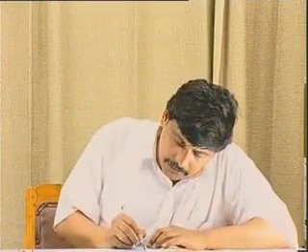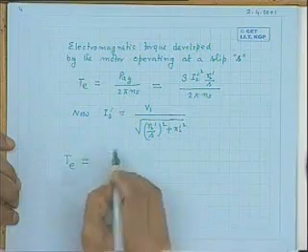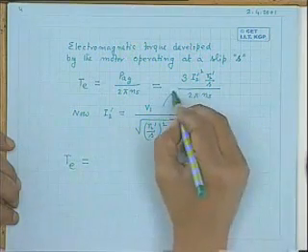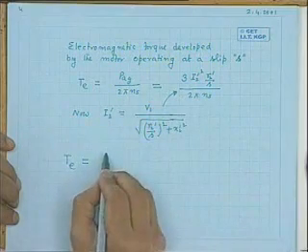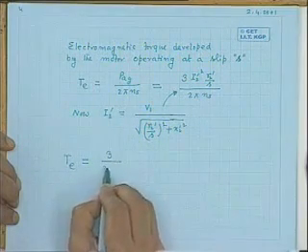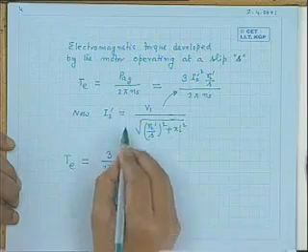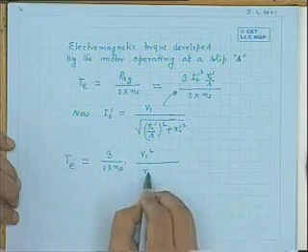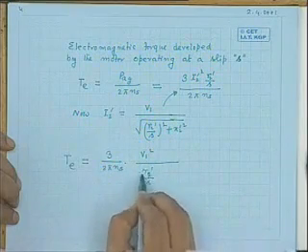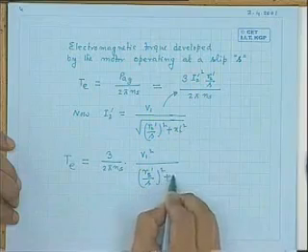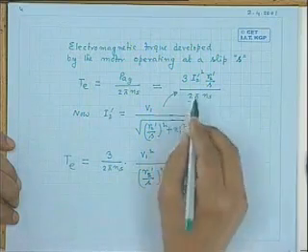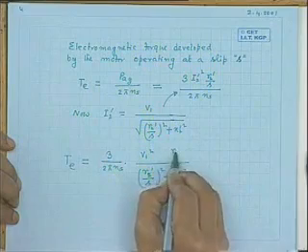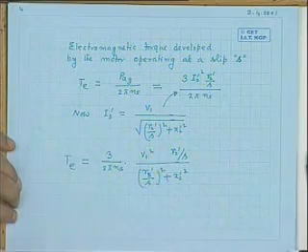Then you know the torque will depend upon machine parameters like that. So the electromagnetic torque developed by the machine, by putting in I2 dashed, will be 3 by 2 pi Ns into I2 dash squared, that is V1 squared divided by R2 dashed by S whole squared plus X2 dash squared, into R2 dashed by S on the top.